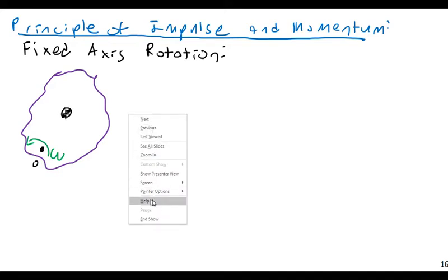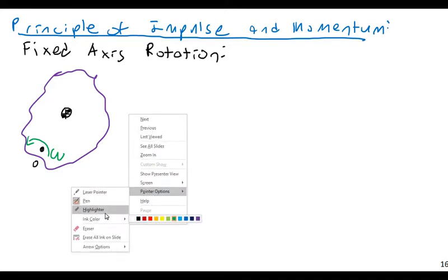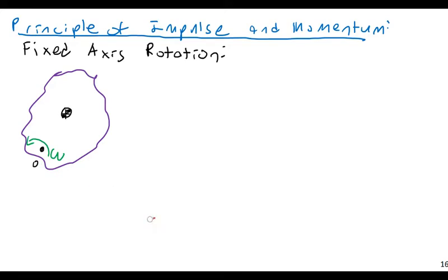And according to the principles we've already seen before, this rotation could be translated into two things. Even though this thing is rotating about O, we could consider it two different kinds of motion. One, a linear momentum about the center of gravity, just like with the rod we saw earlier, m v bar, and I omega.